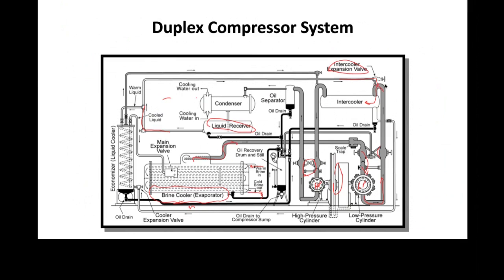Now, maybe we put a little bit too much in there, and if we put too much in there, it's going to accumulate on the bottom, and you'll see where that goes shortly. We're actually going to grab that liquid at intermediate pressure. And by the way, again, this is now at intermediate pressure. So we're going to grab some intermediate pressure liquid that's overfed, and we're going to use it.